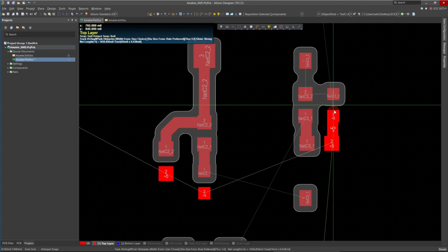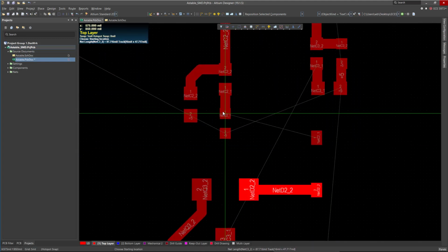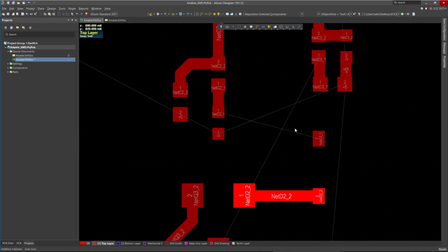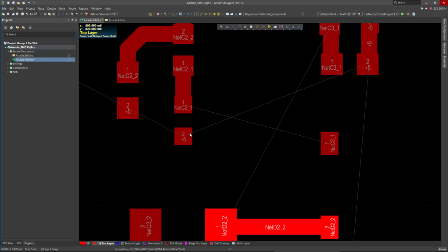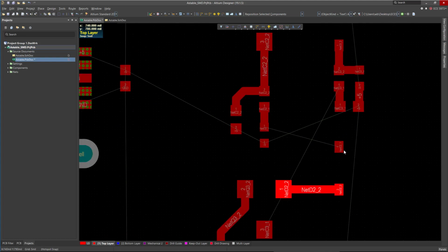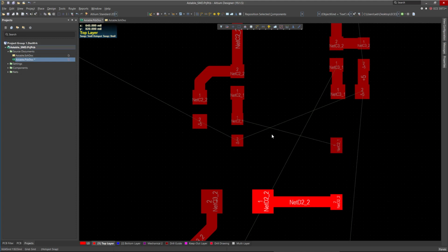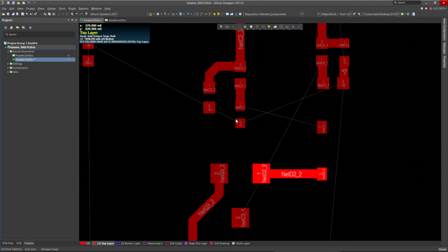These are going to the 5 volt. Let's do that very fast. Okay, now here we have a power supply trace, and we have another trace. This belongs to the switching circuit. Which one has a priority? Always when you have high-speed signals, they have a higher priority than other low-speed signals. Data buses have the highest priority.